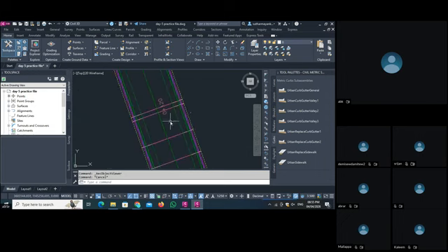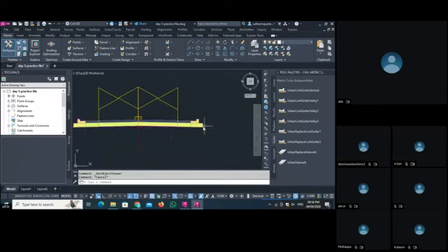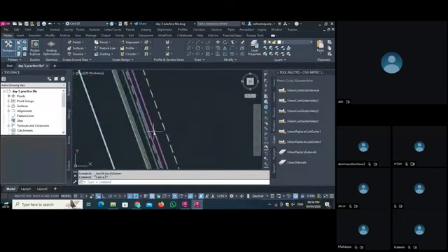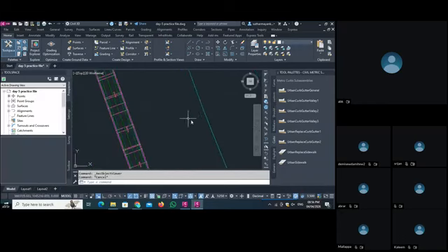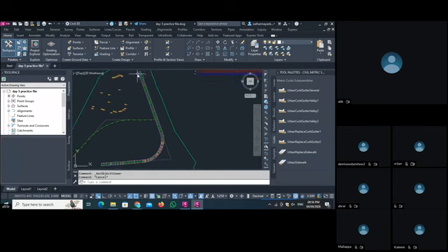So till we create this, now I give the daylight also. Why daylight? Daylight is used for the cut and fill criteria. As I provide the daylight here, what does daylight do? Daylight starts with this corridor, and the end of the daylight is this surface. So on this surface, where our road passes, daylight shows us what is the cutting area and what is the filling area.